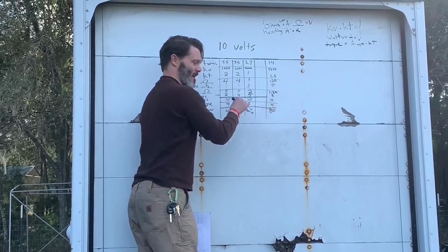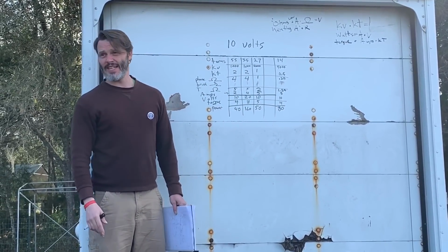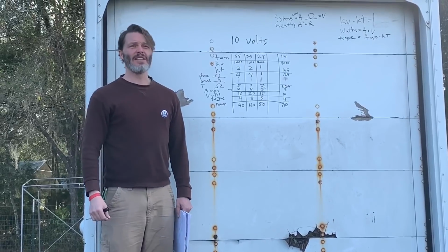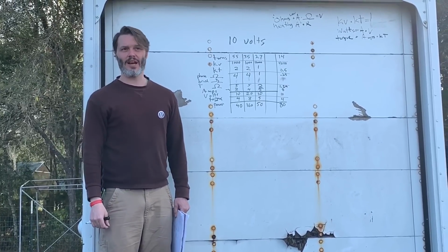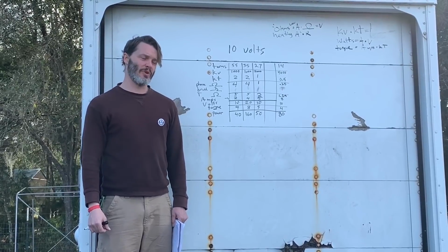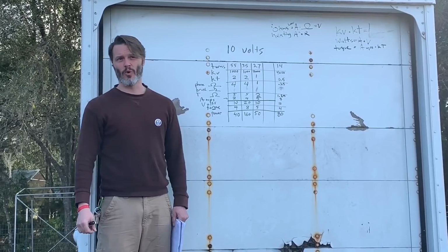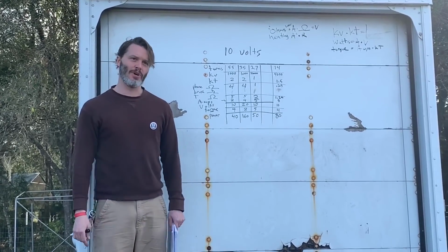And what would happen is all we have on this side, the phase side, is the ESC. And the ESC is going to be on the range of 1/10 of an ohm or 100th of an ohm, depending on how large the ESC is. So something like a Mamba X, the phase resistance on that one is 0.0012 generally, or 0.0014. And then you add in the wire lengths, it's not much more.